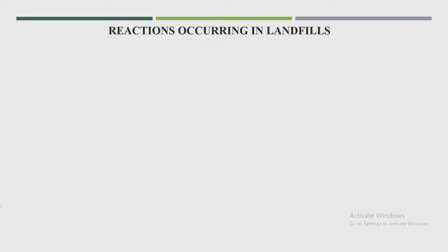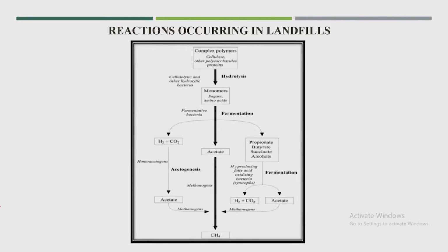Now, what are the reactions occurring in the landfill area? The major ones are anaerobic only. Hydrolysis and fermentation are possible, and finally after the acid phase the methane will get produced, but the quantity is not that large, and the pH in the entire waste material will almost always be in the acidic condition. So, the concentration of methane also will not be that high.